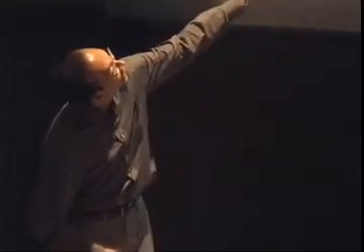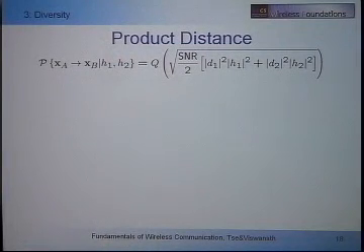See, every little thing I tell you is pretty simple. But as I build on top of that, it gets a bit more complicated, a bit more complicated, a bit more complicated. So deep fade event is the event in which the received SNR is less than 0 dB, essentially. That means inside the Q function, this thing is less than 1, of the order of 1. That means that this thing should be less than 1 over SNR. That means roughly this thing and this thing both are less than 1 over SNR. Same order of magnitude. Deep fade when both components are dying on you, right? Both the vertical and the horizontal is squished.